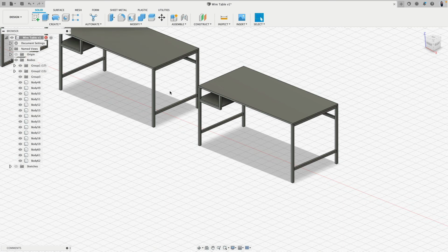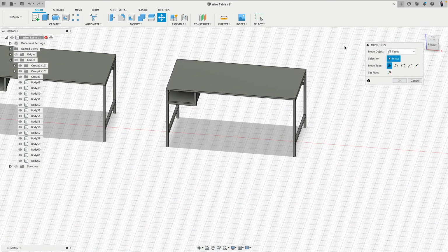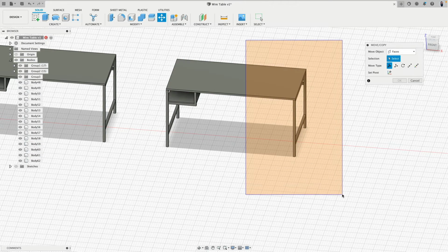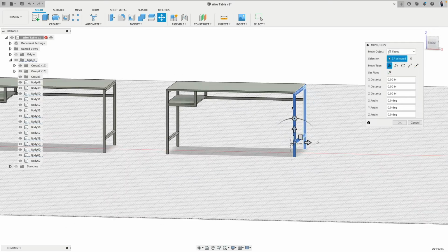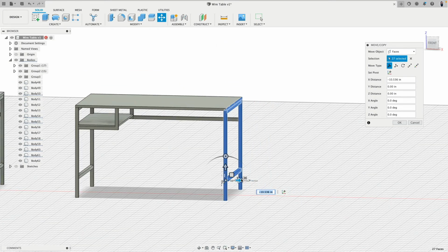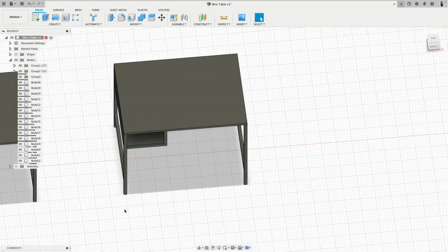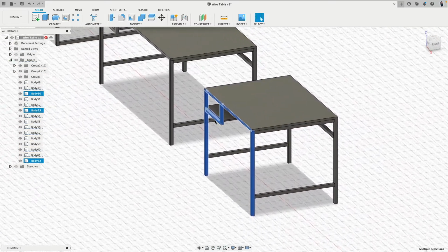How do we do this? This is actually pretty easy. So we go to move face, and now the trick is right to left. You see what's selected, or left to right. Look at that. You see only all the faces here I selected over are selected, including, for example, this cap face. So this all goes over -20. Very nice. And then let's do the same, maybe from the top view. There we are. This is good.